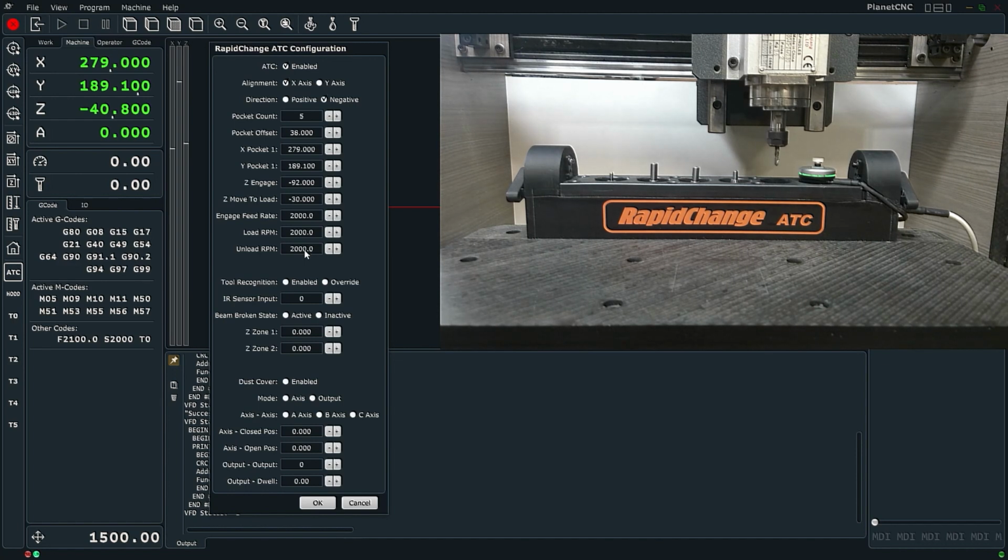One of the biggest mistakes that people make, and it's perfectly understandable, is being used to running your spindle at 12,000 plus RPMs, maybe 8 or 10, and you go to a lower RPM, it's difficult to really judge where the spindle is actually spinning at if you don't have a tachometer or something, because if you try to engage the socket at 4,000 RPMs, you're going to destroy it.